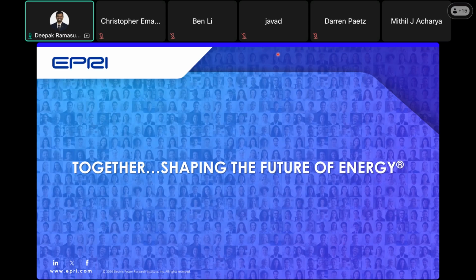Yeah, so the response of grid forming to faults is at the moment non-standardized. In contrast, for non-grid forming, the response to faults, especially with IEEE 2800 coming out, there's a semblance of standardization. For grid forming right now, there's no real standard behavior to faults that exists. As a result, the behavior can be quite different because it depends upon the current limiting method they would have. It depends upon, for unbalanced faults, how they are controlling negative sequence current and what kind of negative sequence current injections they have into the network.